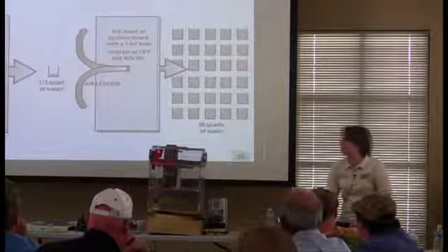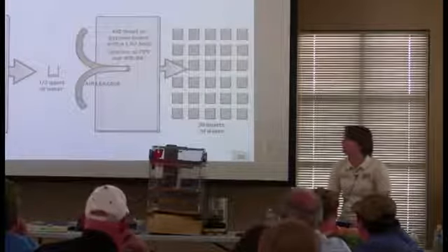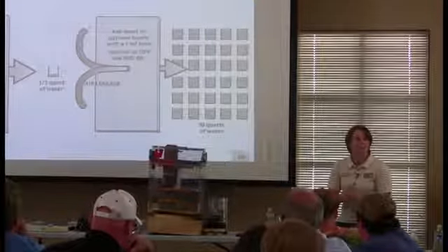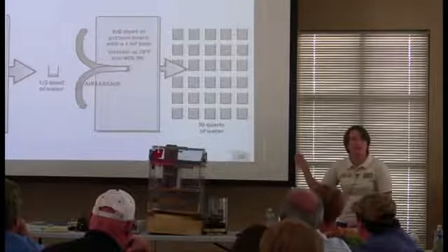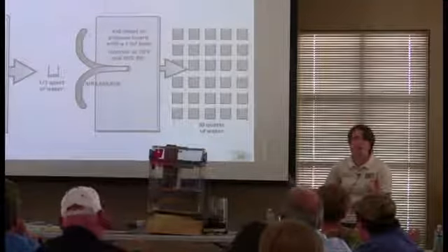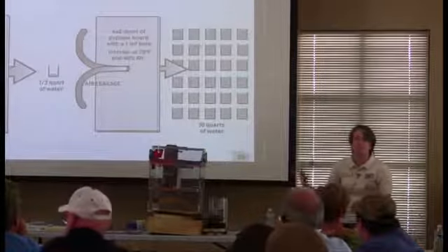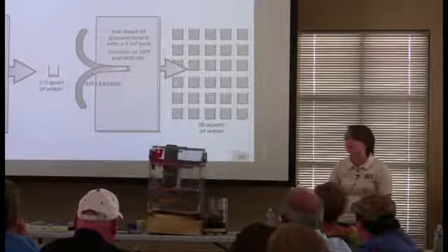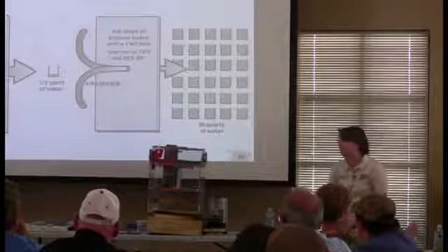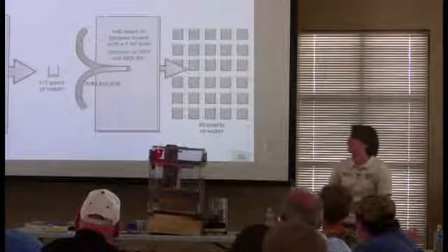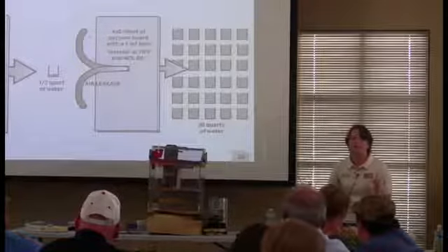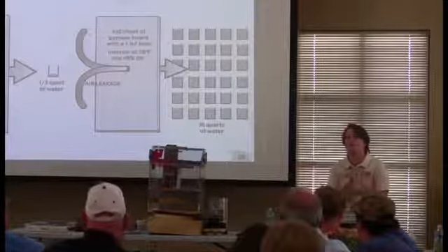I can't say historically, but in the past we might have thought vapor diffusion was the big driving force for moisture inside the building. And that just really isn't true. That's what we're learning up here with this graph. Vapor diffusion only accounts for 1/3 of a quart of moisture coming into a home during the cooling season, or the summer season. Air leakage, however, can be responsible for up to 30 quarts of water. So that's a significant 90 times more water through air leakage, through infiltration, through humidity, than vapor diffusion through a wall.